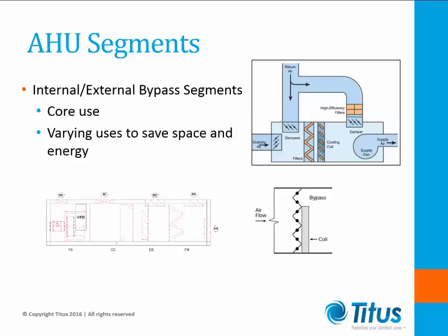The outside air is directed into the mixing section of the unit. The desired amount of return air is then introduced downstream of the cooling coil to mix with the supply air temperature up to desired levels. The remaining return air is discharged into the mixing section with the outside air. When using an internal bypass, the unit will be fitted with face and bypass dampers. The dampers control airflow and modulate supply air temperatures by bypassing around the coil.